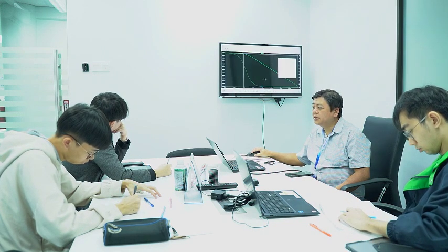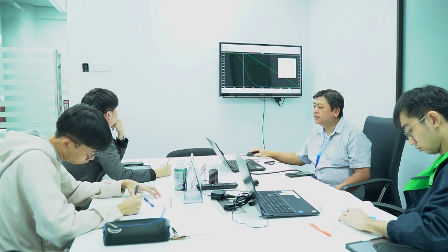Here to here is 180, here to here is 180, so the total is 360 for 1 megahertz. If my input phase shift is 30 degrees, then from 30 degrees I can back-calculate the delay between my input and output signal. So the phase shift is an important parameter, not only for stability check, but also for knowing the delay between input and output.